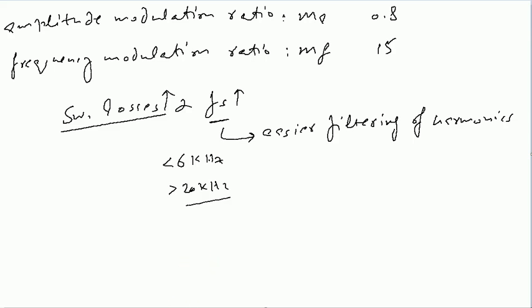Also, if during the design of an inverter the optimum switching frequency comes out between this range, which we do not prefer because of the audible noise, we intentionally increase the switching frequency up to 20 kilohertz. Although there would be some switching losses, there would be no audible noise.